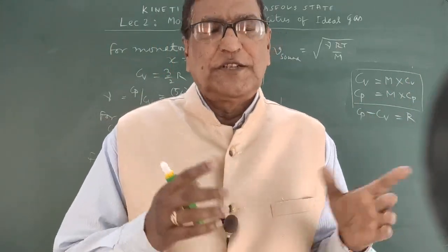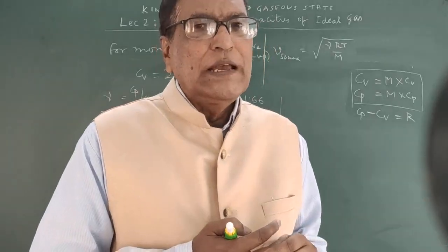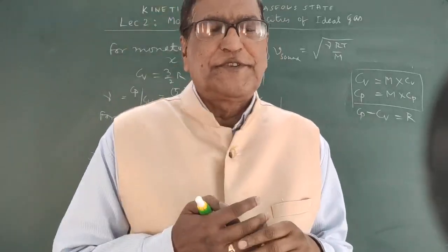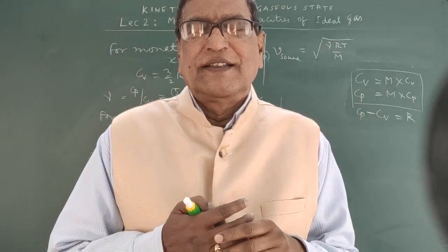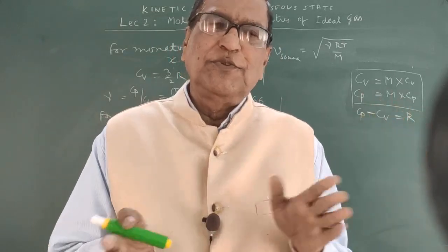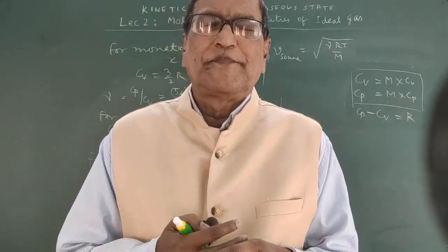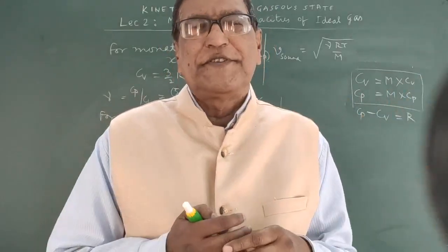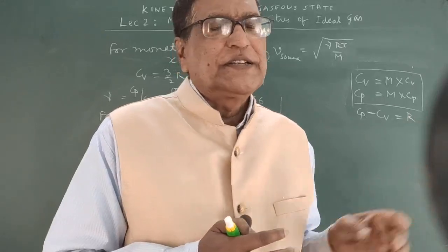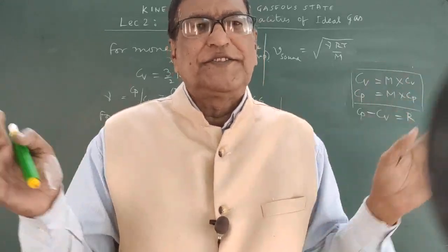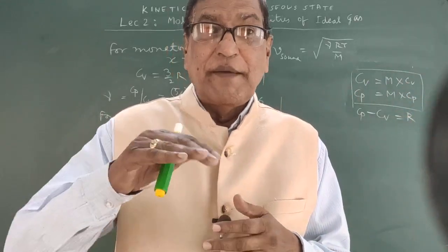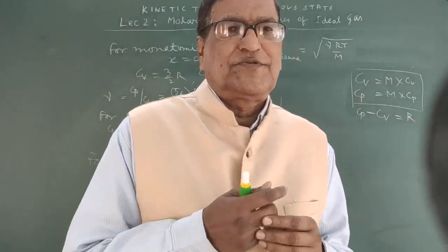But at high temperature, the temperature will affect the value of Cp and Cv. With the increase in temperature, the Cp and Cv values will also increase as vibrational energy begins to contribute.